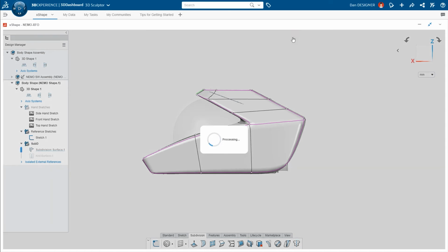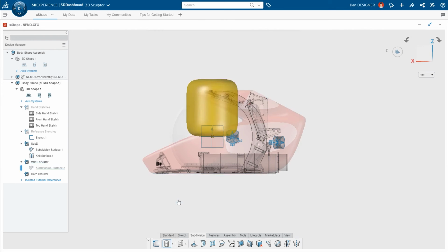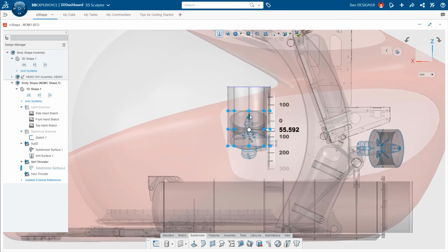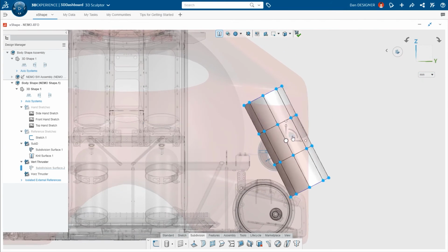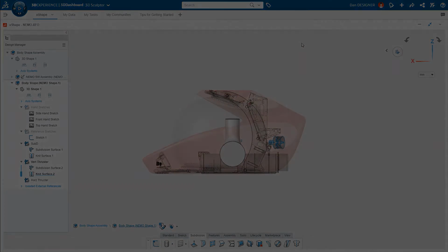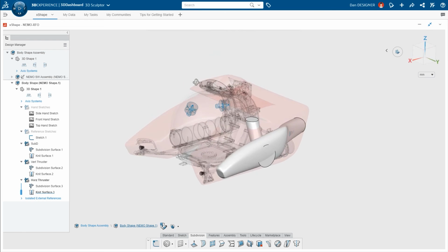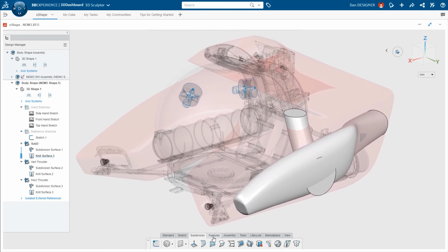He'll prepare a set for each one, not just for organization, but also to sever their dependency on the order they exist within the design tree. Using the cylinder shape and automatically creasing each end will make it easy for Dan to locate the first pathway in relation to the vertical thruster. In a similar fashion, Dan duplicates the process of modeling the negative space required for the horizontal thruster. There are now 3 separate solid bodies that can be combined to form the final shape.